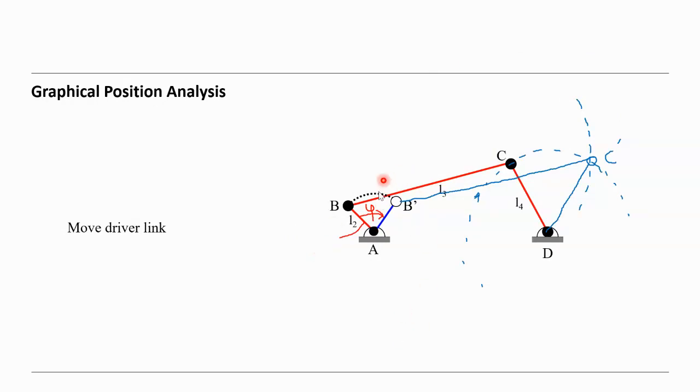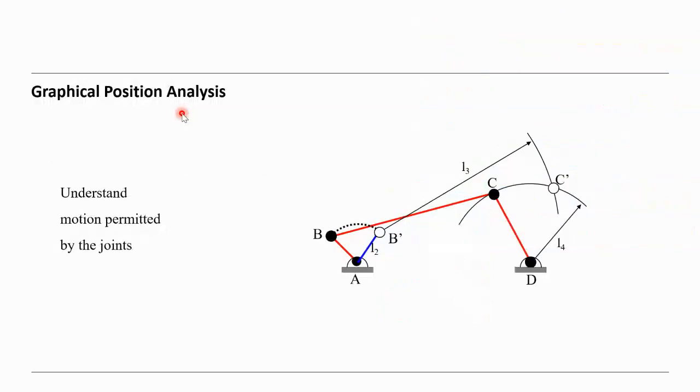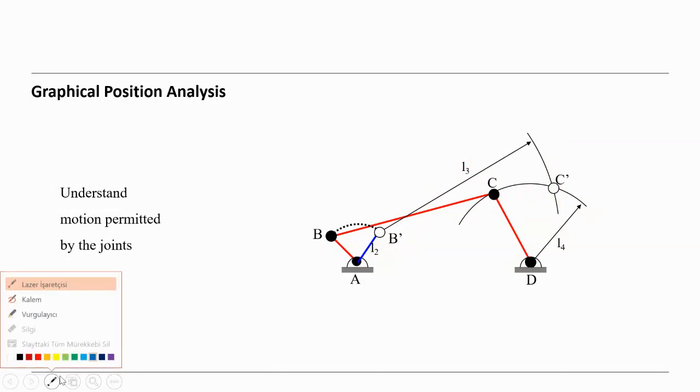The question was, from the point B to B prime is given already, and we take the compass and draw the circle here at this distance, and using also our compass, we draw another circle here with the center of B prime. So then this is our L3. So then the new position is like this.